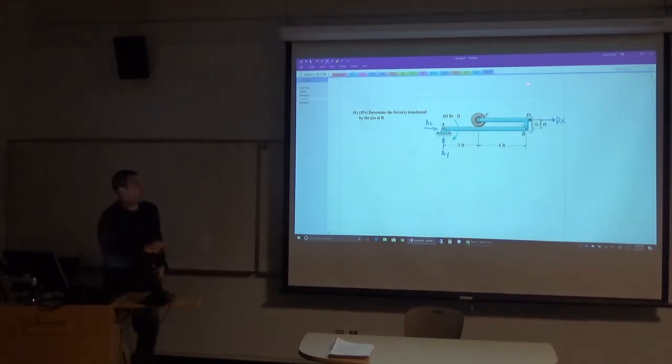Okay, so I've made a section cut there. Where should that section cut go? Like up through this member right here? How many unknowns do I get just from this cut right here through the pin? 2. Is member AB a 2-force member?